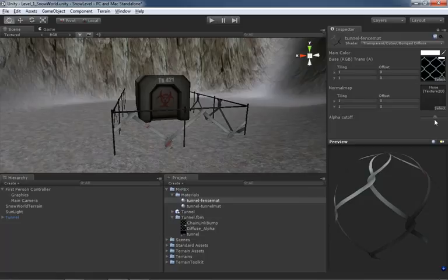Right. The alpha cutoff is a really good way to fine-tune if you're seeing some fringe artifacts on your texture to remove those. If some stray pixels are coming in, it's a great way to make those disappear. Fortunately for us, we're about to crank the tiling way up. And in doing that, that's going to make everything really small. And so if we had any little fringe artifacts coming along, unless they were really bad and really obvious, they wouldn't really be all that visible anyway.